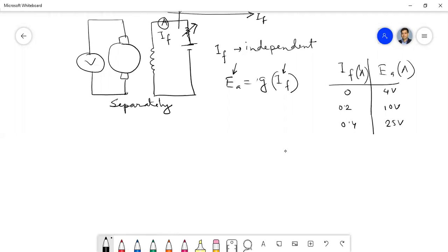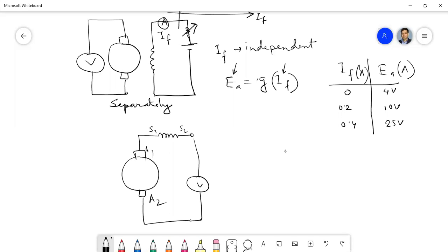কিন্তু আবার একই পয়েন্ট, যদি আমরা ওসিসিটাকে ড্র করতে পারতাম তাহলে কিন্তু একই ওসিসি পেতাম। But in case of this series excited generator, we can't draw any OCC because series excited generator doesn't generate any voltage. Why? Because the field will not be excited at all. Suppose this is a series excited generator, and you have connected a voltmeter there. So that means it's open circuit, isn't it?